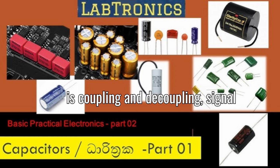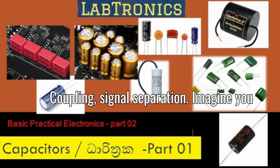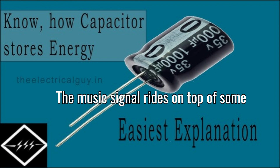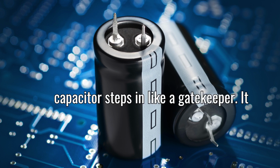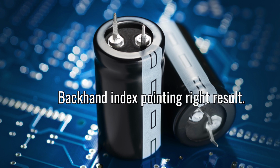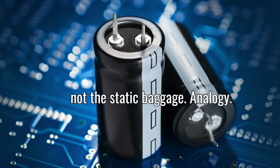Number 3 is coupling and decoupling, signal separation and noise reduction. Coupling, signal separation. Imagine you want to pass music, an AC signal, from your phone into a speaker amplifier. The music signal rides on top of some unwanted DC level, like static voltage that can harm the next circuit. A capacitor steps in like a gatekeeper. It blocks DC, the junk you don't want. It passes AC, the music, the actual signal. Result: your amplifier gets only the clean sound, not the static baggage.